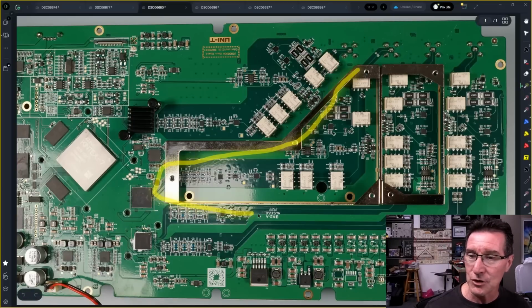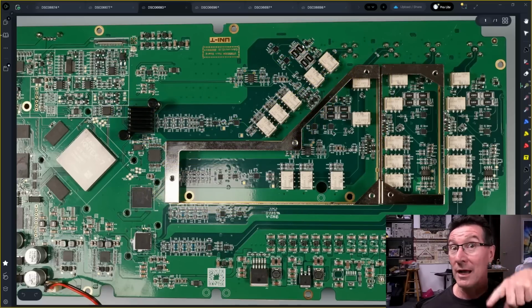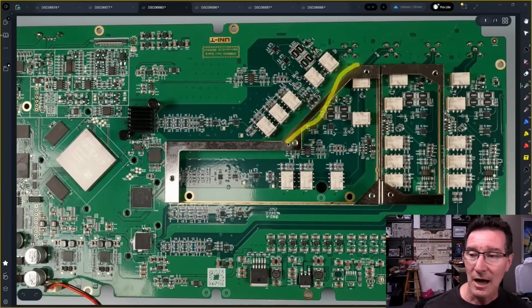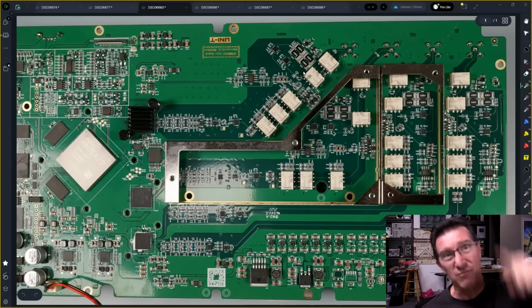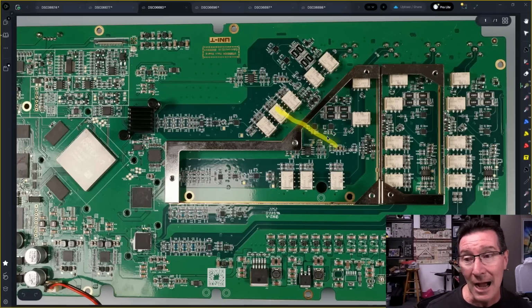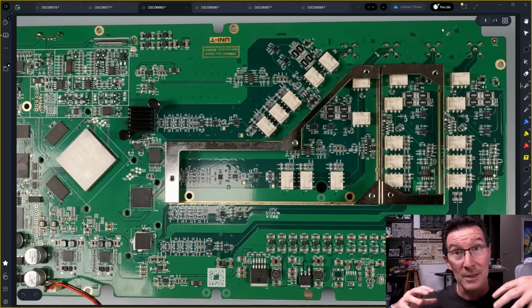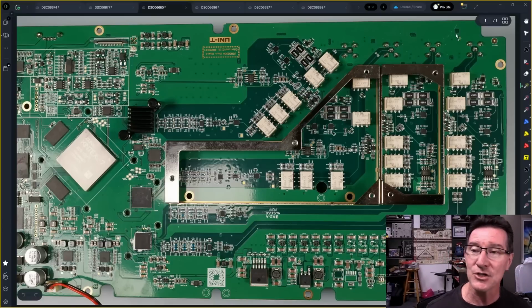So, but why is channel 2 special? It's because this is low impedance and high voltage swing, so when another channel right next to this channel is switching, could be a big square wave, boom, boom, boom, you know, plus minus 12 volts or something, then that can easily couple into the channel next to it, right? So you want to shield one channel. So this is not from any external noise from the instrument. It's designed to stop coupling between channels like this. It goes in both ways, like that.